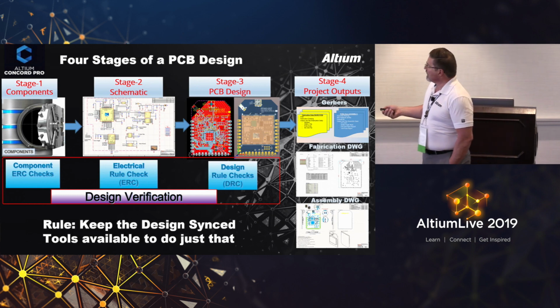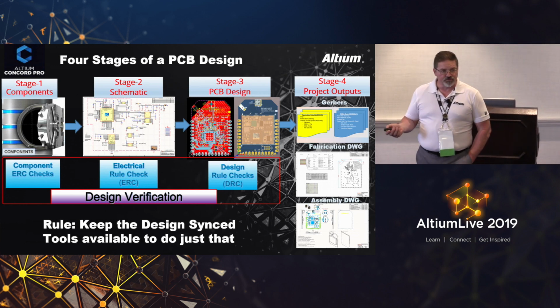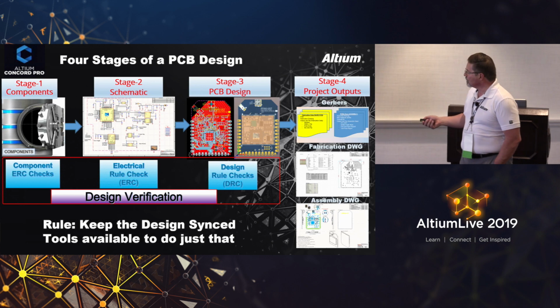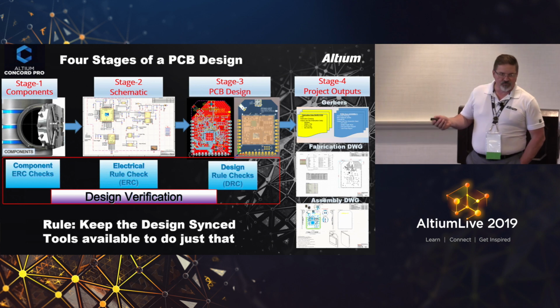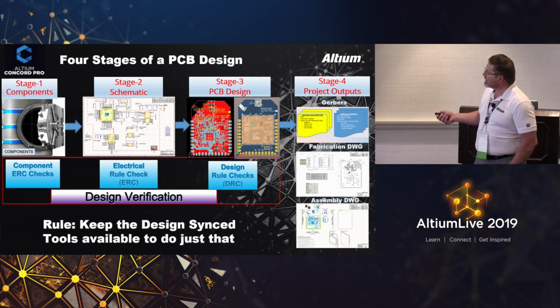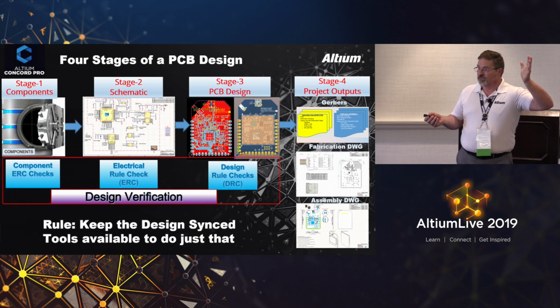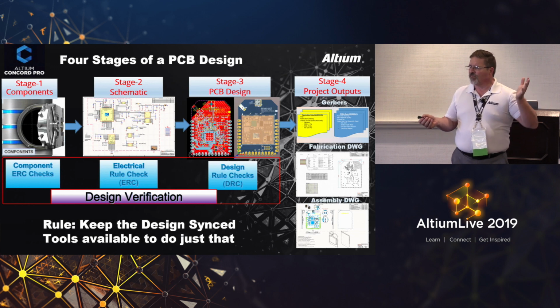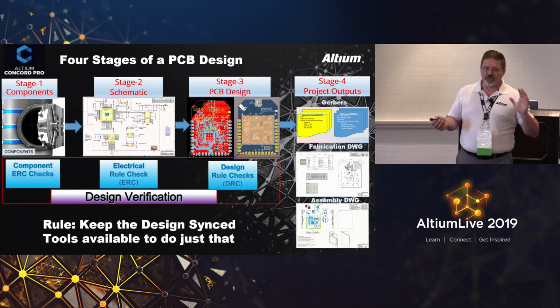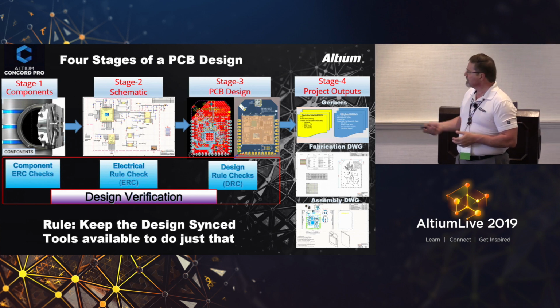Your components should not be released or allowed to be used in designs without being reviewed and verified, okay? Same thing with ERCs. How many of you are familiar with ERCs? How many of you run ERCs? Only a few of you, okay. ERCs are all very important, guys. Learn to use those ERCs.